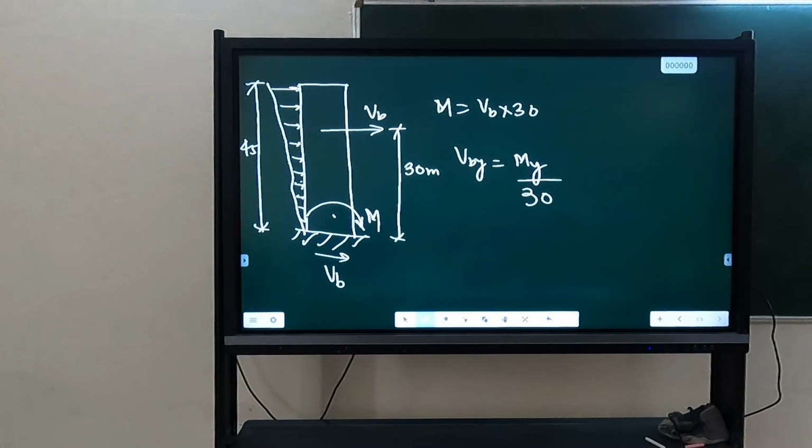Limit moment capacity. Okay, that is ultimate, with factors of safety and characteristic strength. What do we have to do? We have to use expected strength and factors of safety 1. Use that, then you will get the ultimate moment.